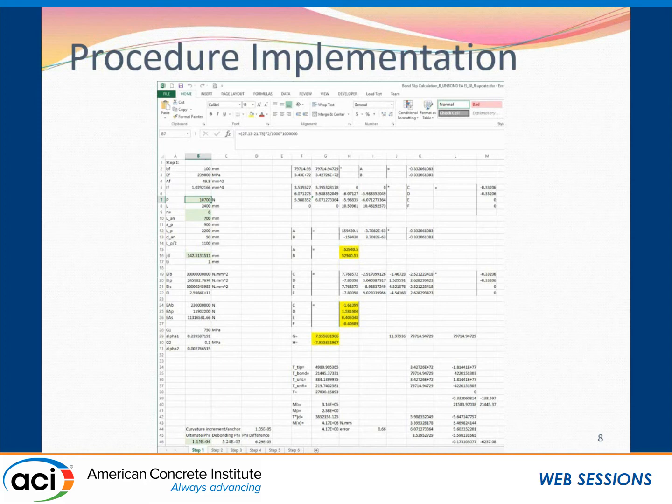Assuming that we are now at the debonding stage at the last anchor, we apply more load there, a load step, and we perform our analysis. We calculate the force in the interface from that, and then calculate the moment in the section. Compare that with the applied moment. We see if we converge or not. If we converge at that step, we move ahead. If not, we reiterate until we converge.